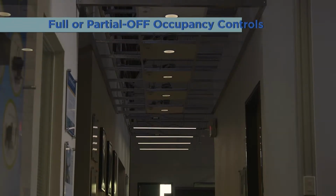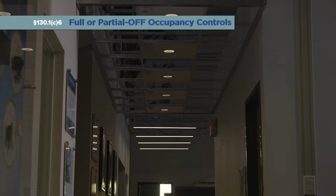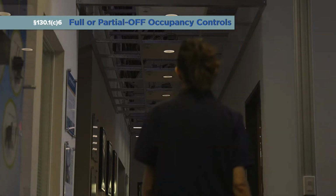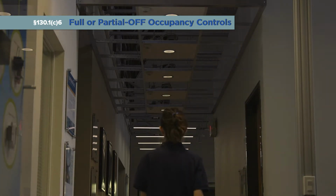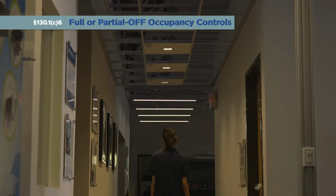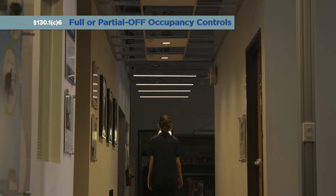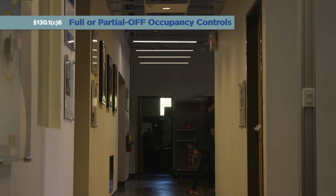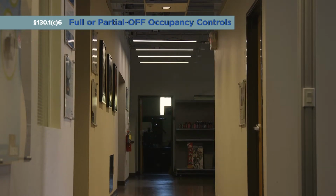Now let's go over the areas where full or partial off occupant sensing controls are required. First, this control strategy is required for aisleways and open areas in warehouses. Lighting should be independently controlled, and occupancy controls must automatically reduce lighting power by 50 to 100% when the area is vacant. It's important to note that full off occupancy sensors can be used to satisfy the control requirements for these spaces. Also, occupancy control should not control lighting beyond the aisleway.